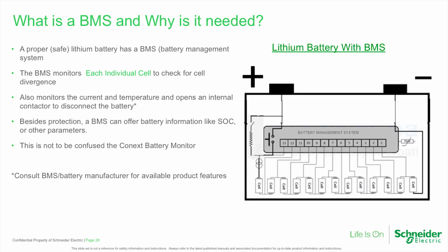So I want to talk about this BMS, this battery management system, because it's real important. Our equipment only connects up to the positive and negative. That's all we really see. We see the voltage on the outside. And with a lead acid battery, we weren't really worried about how all the little 2-volt cells inside the battery shared. When the battery wore out, it wore out. A lithium battery, though, the lithium cells have much less of a sense of humor than a lead acid cell.